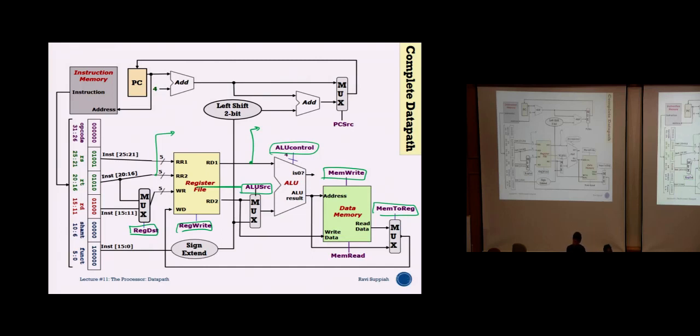Because you need a 32 bit address to jump to. So you're assuming your PC's first 4 bits is different, but the last 28 bits is all 0? No, we assume the upper 4 bits will be the same, and the other bits can change. That's why we take the 4 bits. Okay.